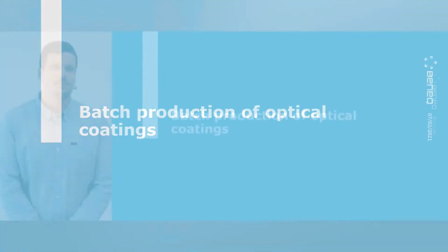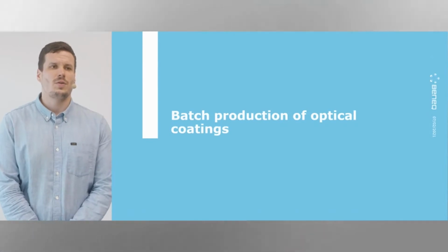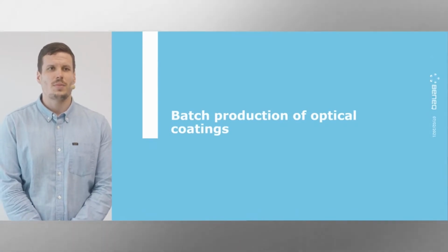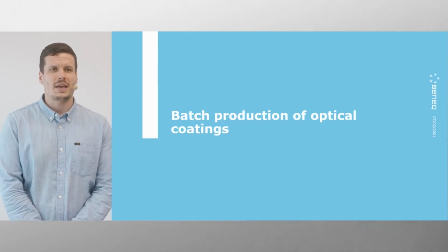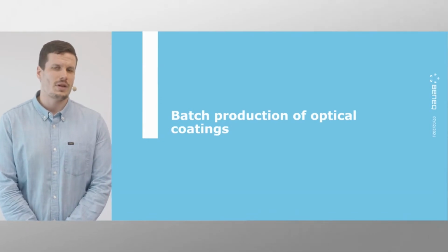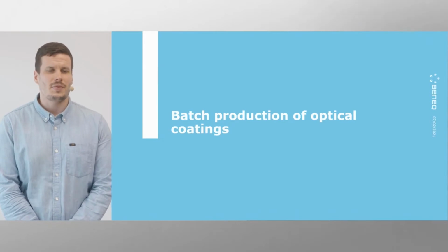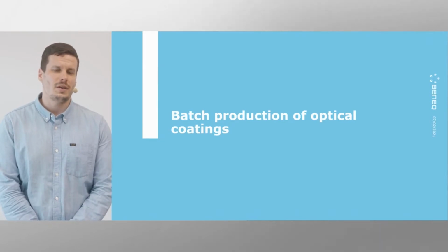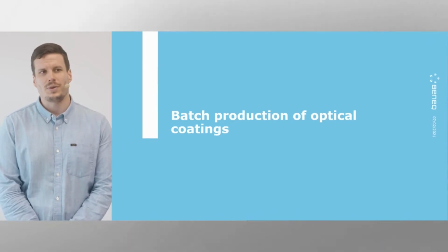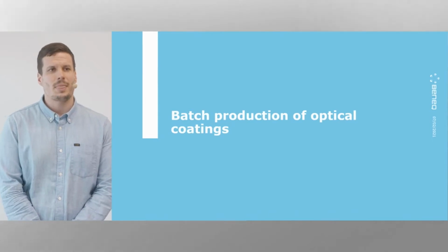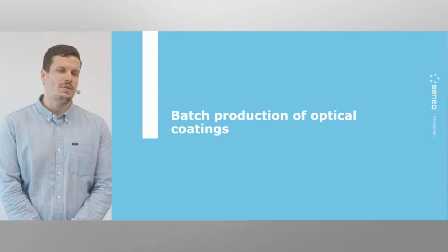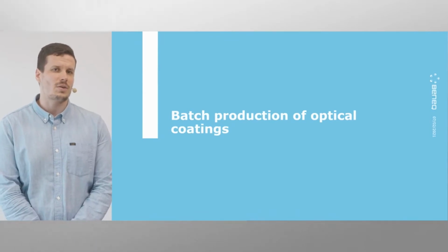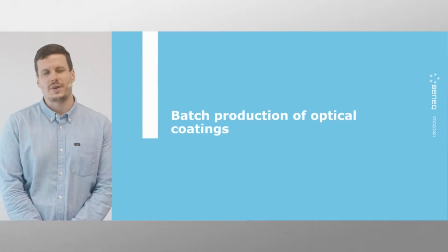Okay, thank you, Sami. So as Sami mentioned, the conformality of ALD is one of the most important features of the technology. In some applications, the surface to be coated can be so complicated that there is simply no alternative way of depositing a reasonable film with any other technology. In many of these cases, one typically aims to deposit only a few tenths of nanometers of high-quality film, such as when passivating a surface, for example.